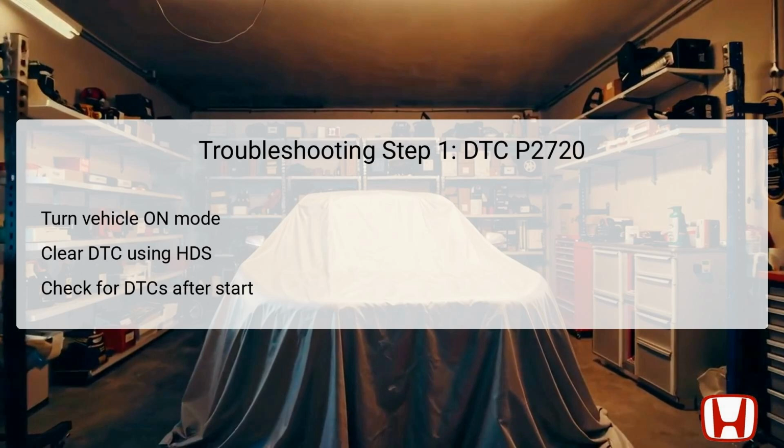Then check for any pending or confirmed DTCs using the HDS. If DTC P2720 is present, it confirms that the issue persists. If not, the problem may be intermittent, and further investigation into electrical connections is warranted.